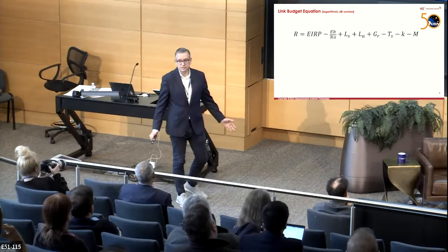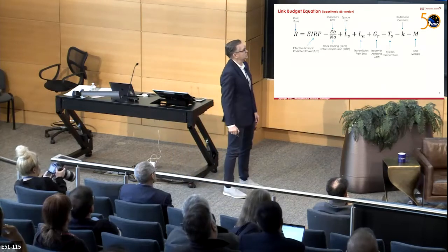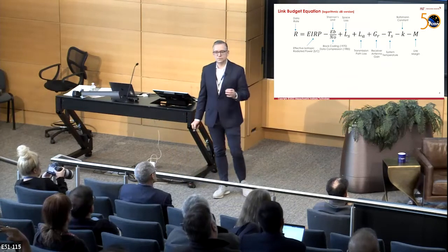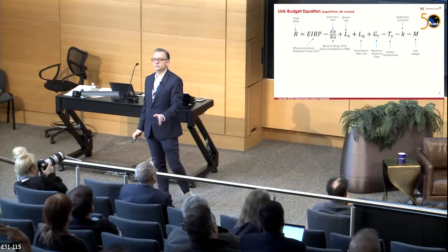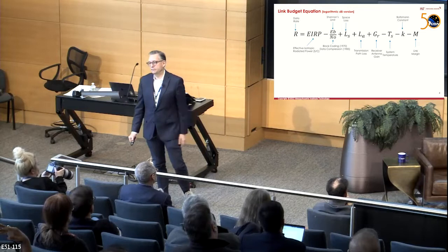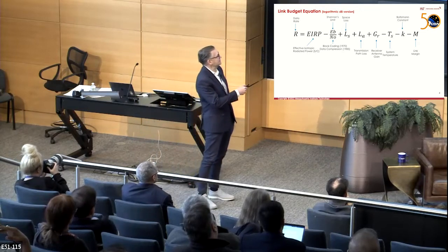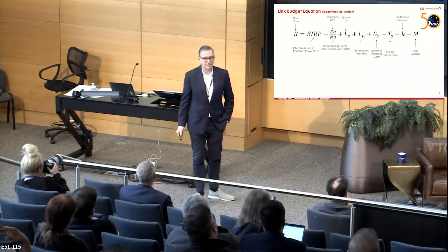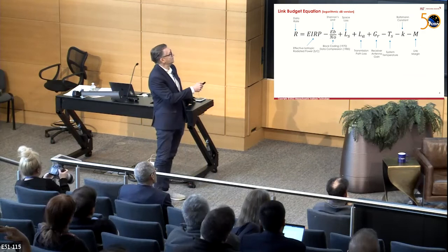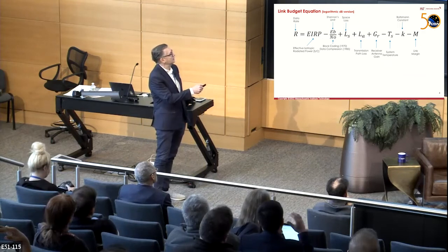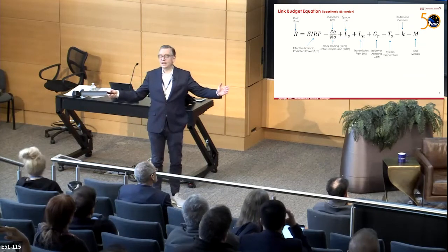and governing equations. This is a governing equation known as the link budget equation. It essentially gives you the data rate, R, on the left side, as a function of its constituent factors or drivers. And this is the logarithmic form, which is nice because everything becomes sums and it's essentially a sum of factors. So how much power is in the signal? Shannon's limit.